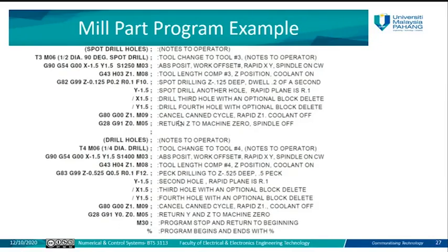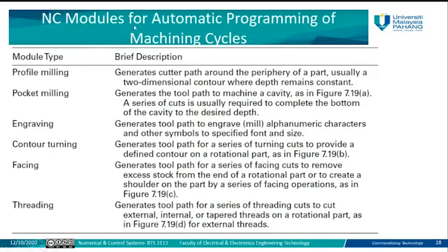For the drilling, there are some already existing canned cycles which are used directly to make a drill with specific tips, and this operation will be repeated automatically by using just one code. When we define one code here, we have several canned cycles for drilling. When we use just one code, this one code will perform a series of operations.